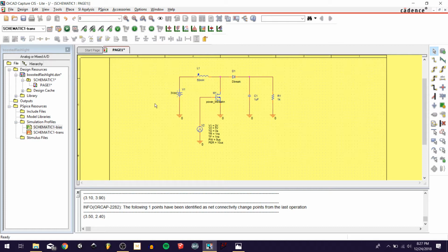So what we're obviously interested in is seeing this output voltage on our simulated load. So I'm going to go ahead and click this voltage level marker, and it's going to give me this probe attached to my cursor. And I come over here, and if I click on the output node, it's going to place that probe marker. My computer's running pretty slow, but it places that probe marker there. And that's the only one I'm really interested in. So I'm going to right click and then End Mode to get out of that. And now it's all set.